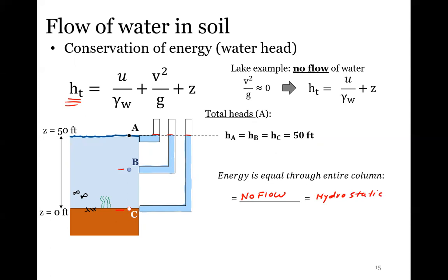So what would happen then if we came in with some pump or something and we decided to pump at this spot and then subsequently lower the pressure head to a lower elevation? We would see water want to move this way, right? And since this is just open water, it would probably move unimpeded. And that's like when you have these little whirlpools at the surface. But if this whole thing was filled with soil, the water is not going to move as quick, right? So we're going to have some resistance to water flow, and that's the important thing of permeability.